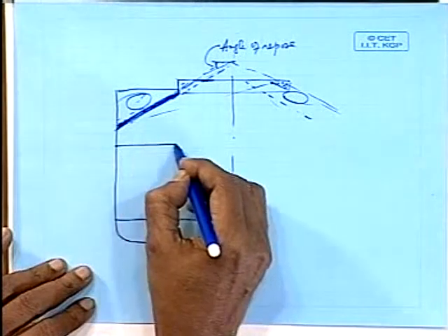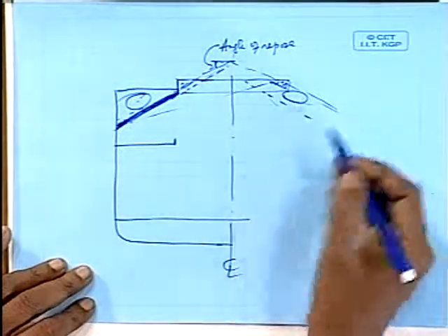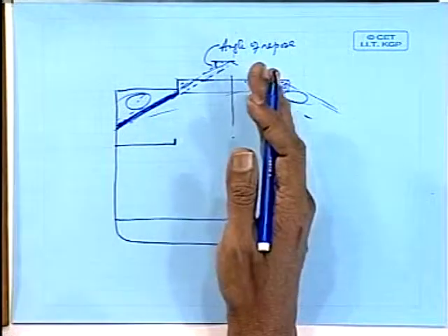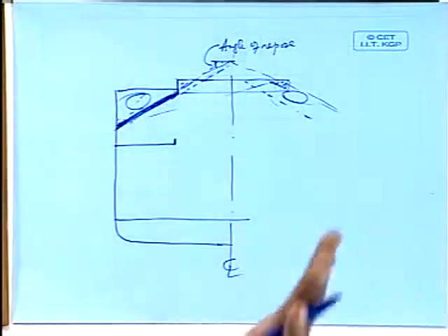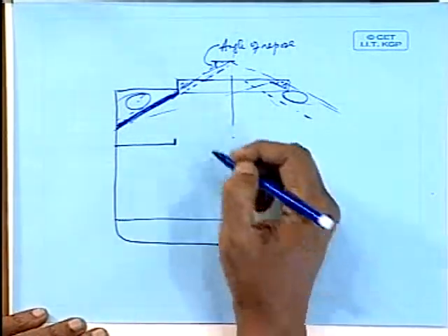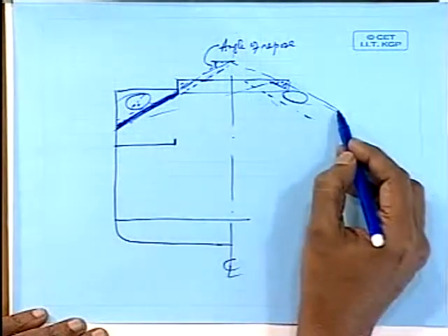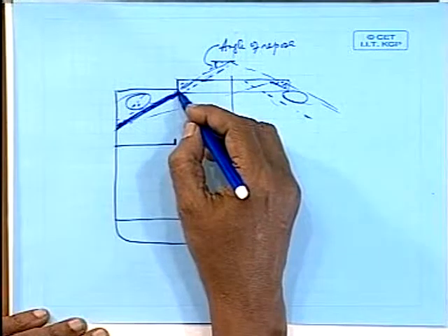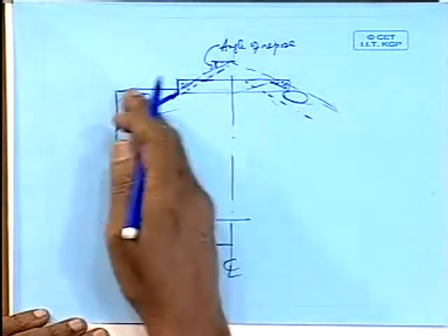But suppose you are carrying grain in a general cargo ship. What can you do? Suppose you are carrying grain in a two-deck ship. Let's consider this, it's very interesting. You don't have this structure because it's not a pure bulk carrier. You require volume, you have space for general cargo. Now what will you do in this ship? This is still likely to shift. What can I do? One thing I can do, can I break this breadth of the ship?